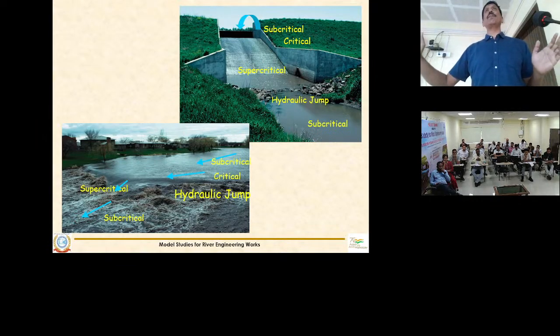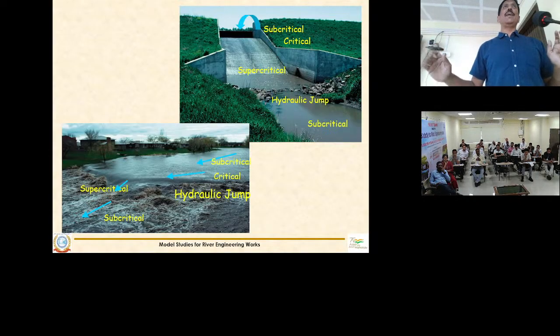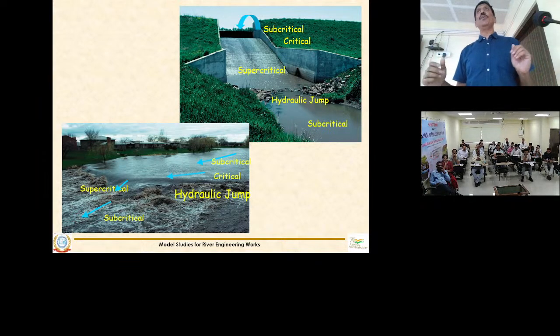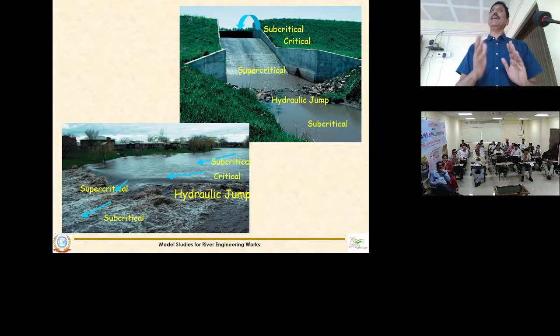So in a short distance of a reservoir, say about 100 to 200 meters, you can witness all these flow conditions. Even at the weir you can witness them. So you have to see what you are modeling. If you are modeling a backwater curve, it is a subcritical condition. But if you are modeling some transition, then it's very difficult to get that in HEC-RAS.